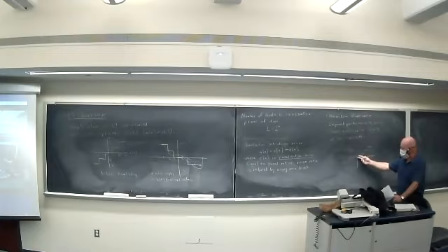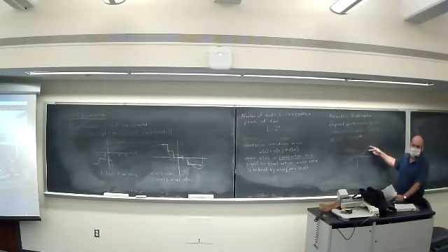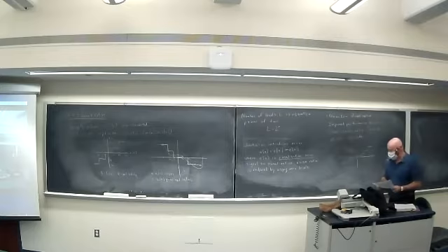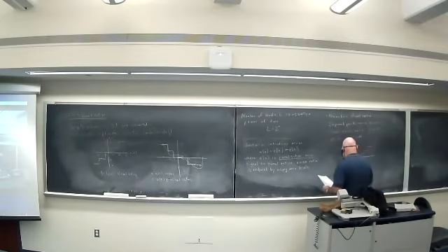Because now, let's say this is 1/10 of a volt. At lower amplitudes, if my step size here is 1/10, my error would be less than half of that, or 50 millivolts. Here at the larger amplitudes, I can have larger errors, maybe a 2-volt error up here, but again, the ear is not as sensitive to those quantization errors at the higher volumes. So this is non-uniform quantization.